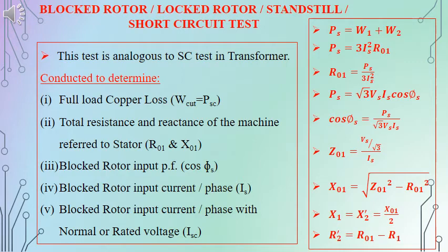From the block rotor test we can also find out the short circuit current for the rated voltage, that is ISC, which is required for drawing the circle diagram.